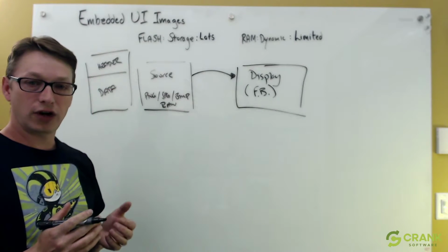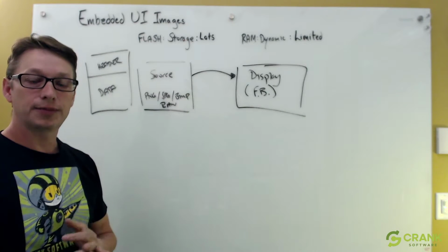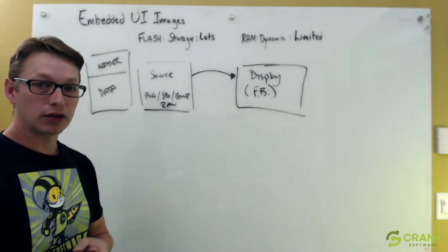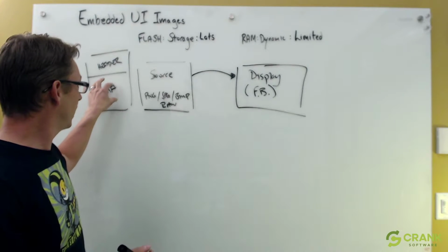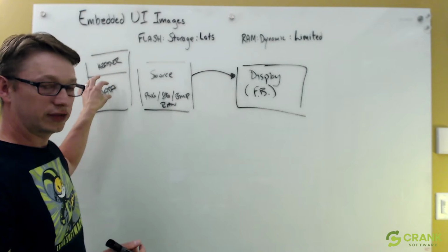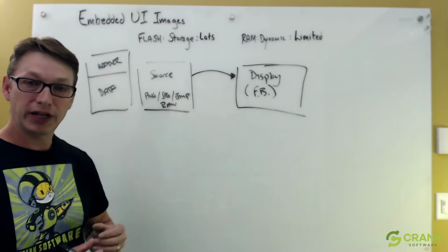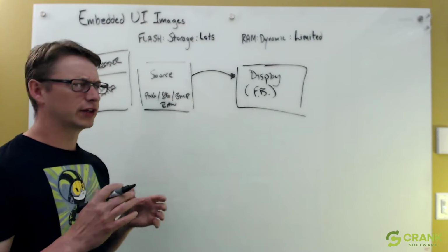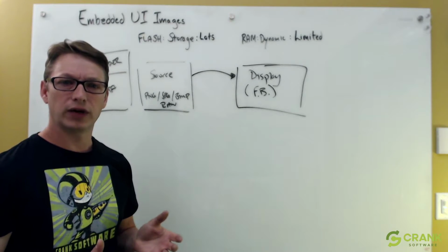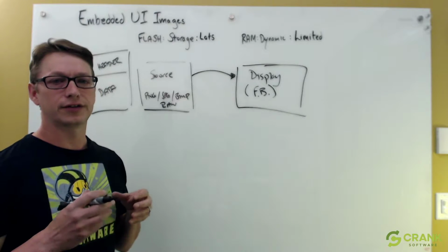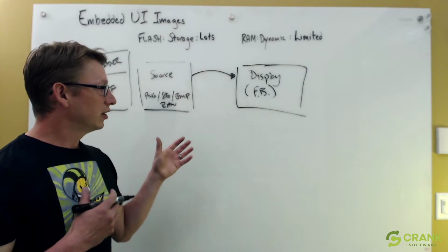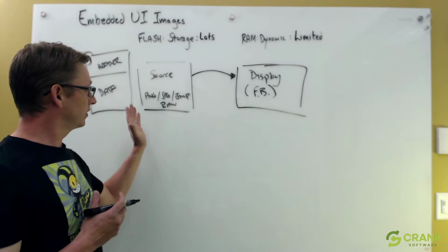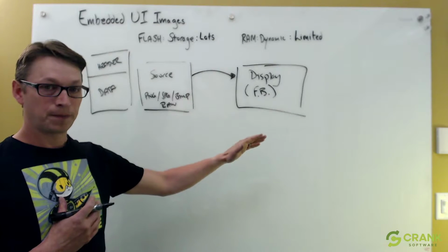The header describes the type of encoding, the size and dimensions of the image, the nature of the color format, and it really tells us how we can get this data decoded and into the display, which is typically a pixel representation, right? There's lots of different encodings for displays as well. You can have palette-based, you can have 16-bit or 32-bit, but generically, at the end of the day, we're really representing colors in the display, so we need to get these pixels across.